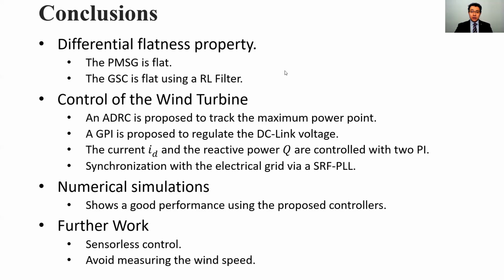To conclude this presentation, we can say that the differential flatness property exhibited by the PMSG and the grid-side converter is advantageously exploited to design an ADRC controller to track the maximum power extraction curve, a GPI to regulate the DC link voltage to its desired value, and also two PI controllers to reduce the copper losses and control the reactive power exchanges with the electrical grid.